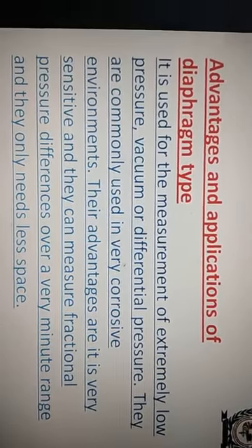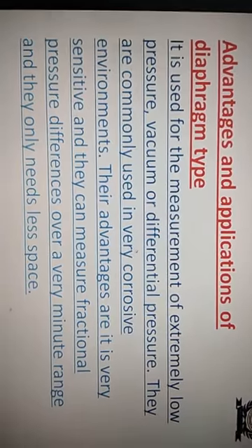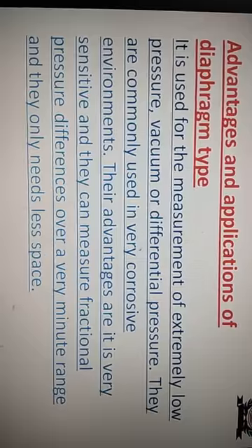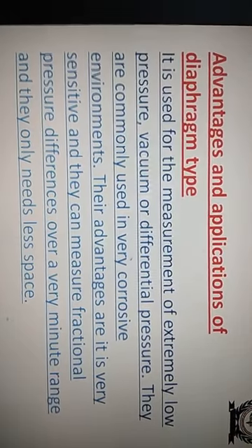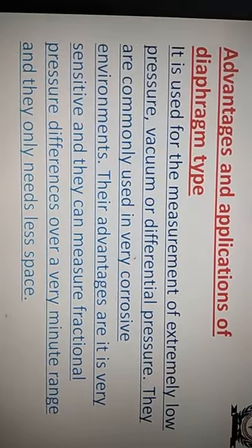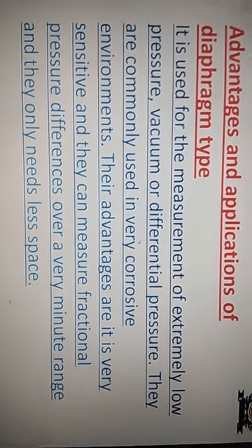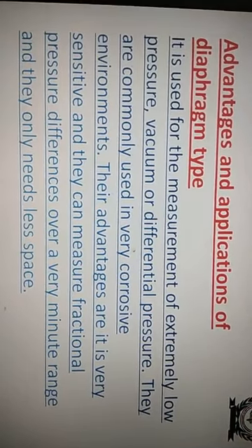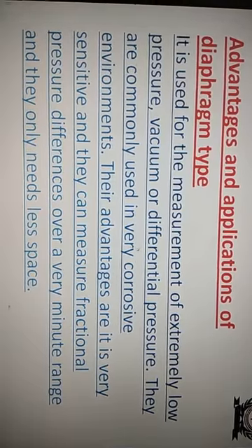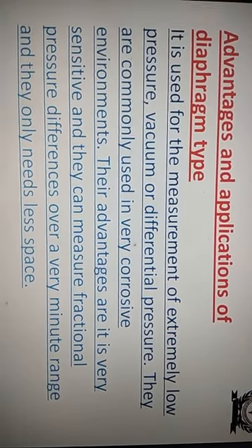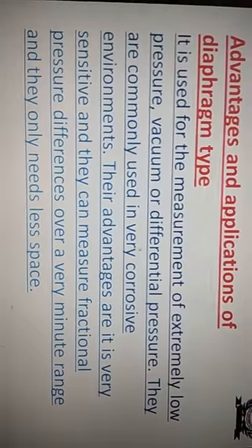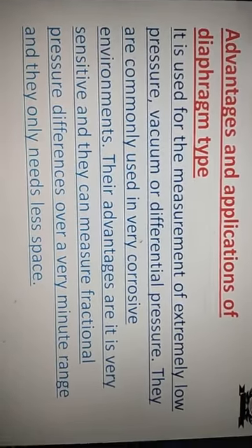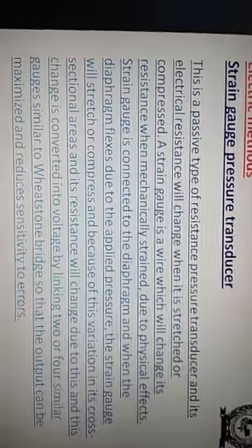Its advantages and applications: it is used for the measurement of extremely low pressure, vacuum or differential pressure. They are commonly used in very corrosive environments. Their advantages are that they are very sensitive, they can measure fractional pressure differences over a very minute range, and they only need less space.